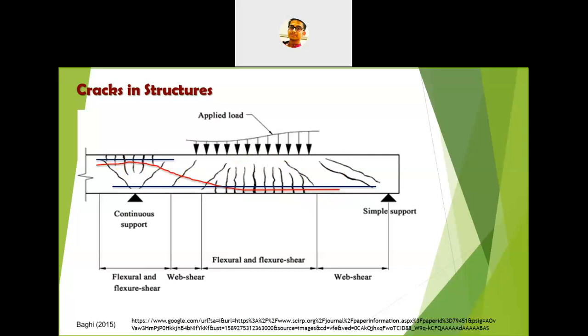Now why am I showing you these cracks in these corrosion mechanisms? Because you see the deep blue color straight lines, let me show you again, these lines and this line. Suppose you consider these as the reinforcing steels or embedded bars. If the bars are coming in between these cracks, the bar will be very prone to different types of deleterious agents. Automatically the chloride or the carbon dioxide will enter through these cracks, and it will initiate the corrosion in the reinforcing steels.